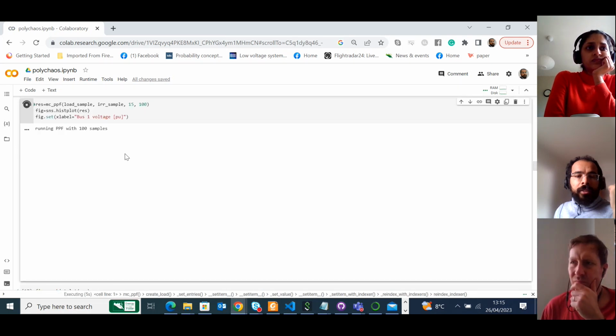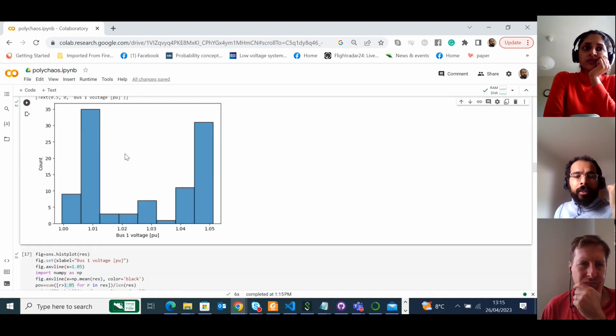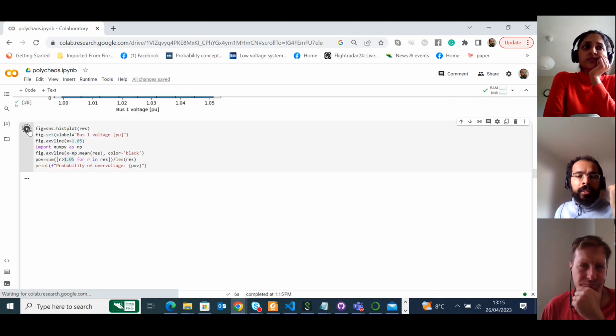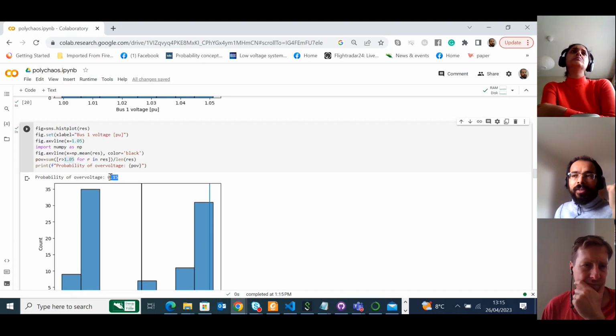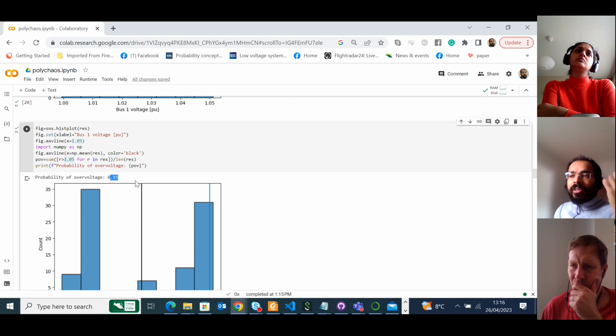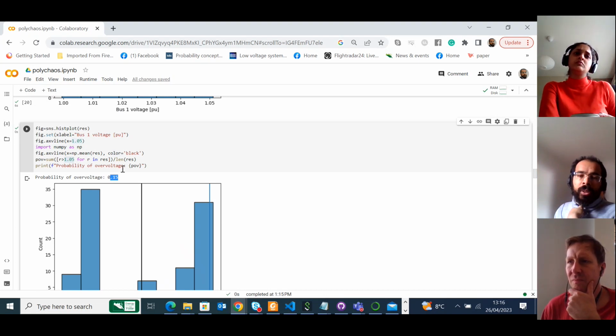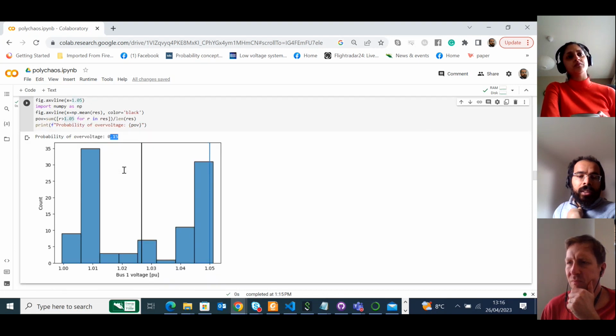This is because in Monte Carlo we need a lot of samples to get very accurate results. If we rely on very few, you see it was 12% before, now I changed the samples, and now it is 0.15. So if you want your result to converge, you need a relatively high number of samples. Then your convergence will be faster between the two instances of Monte Carlo simulations.